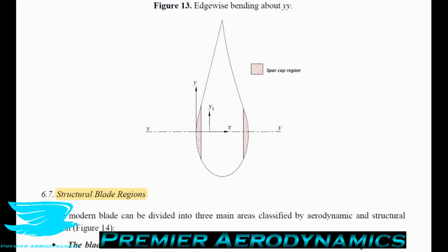So I just want to quickly mention here, if you are doing wind tunnel experiments, or any experiments really with air, you need to make sure you're measuring the density of air. The reason why is because it changes from day to day. The temperature, pressure, and humidity all change the density of your air. A lot of aerodynamicists assume that it's just 1.2 or 1.225 kilograms per meter cubed when they're doing their experiments, but it's almost never that.